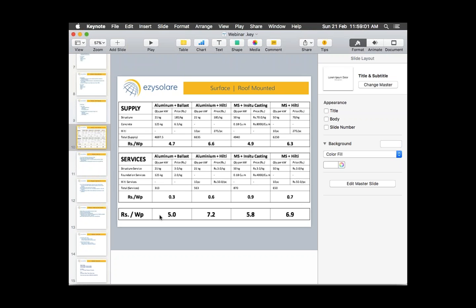In single axis, east to west tracking makes much sense because your tilt angles are less. Now, take the same case if you go towards Delhi or Uttar Pradesh or Punjab, where the latitude is high. In that case, with single axis trackers, you lose the south advantage because they will be tracking east to west. So whatever generation gain you get, you're losing something on the south. So on the same structure, you create a little bit of tilt towards south, though it doesn't track, but stays at, let's say, a 5-degree tilt. Here it is called a polar structure.